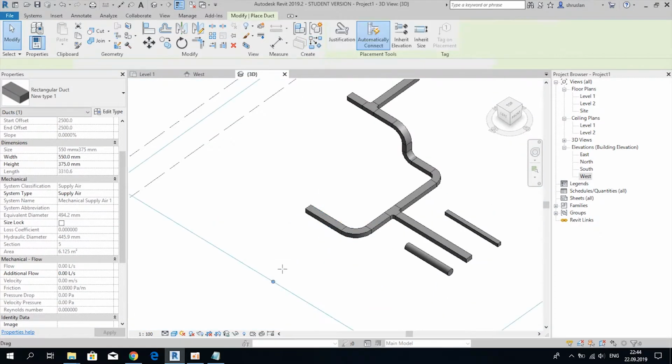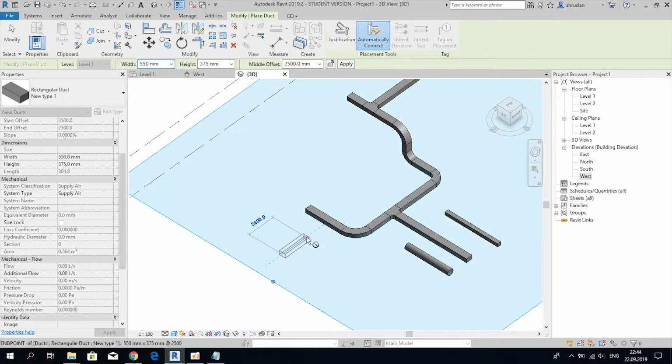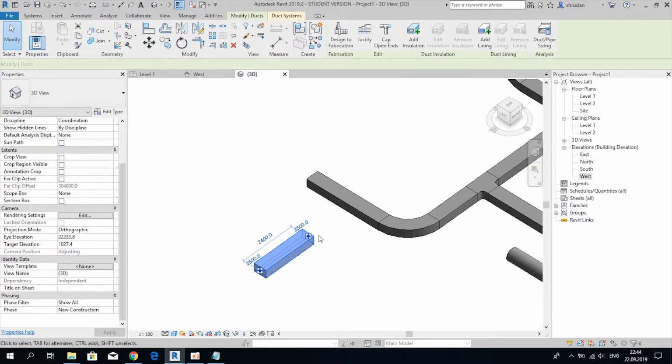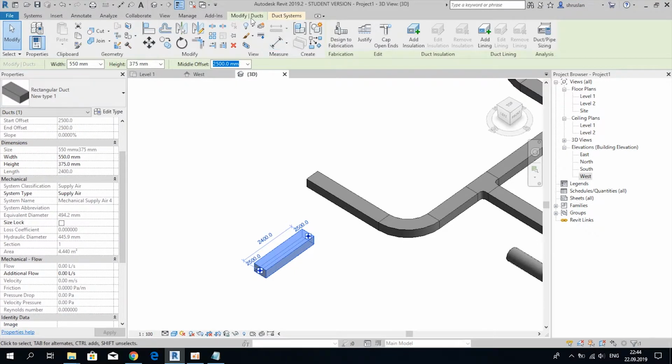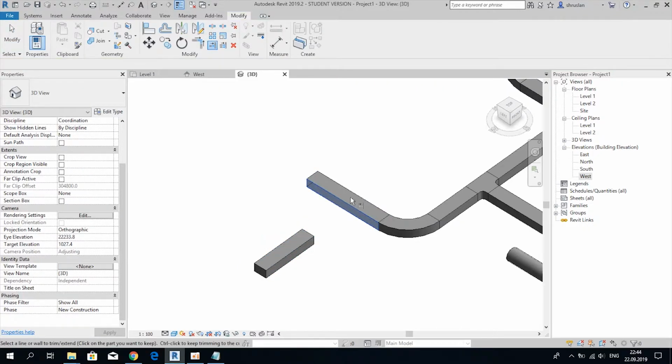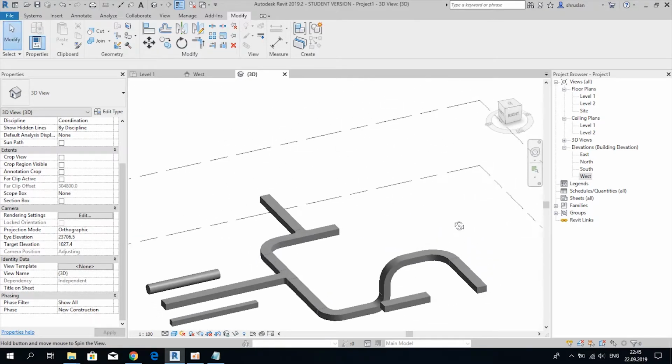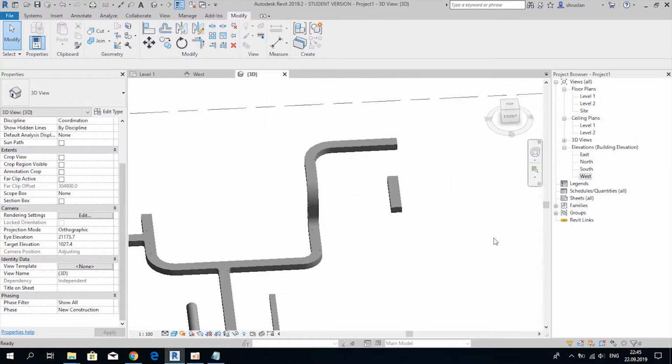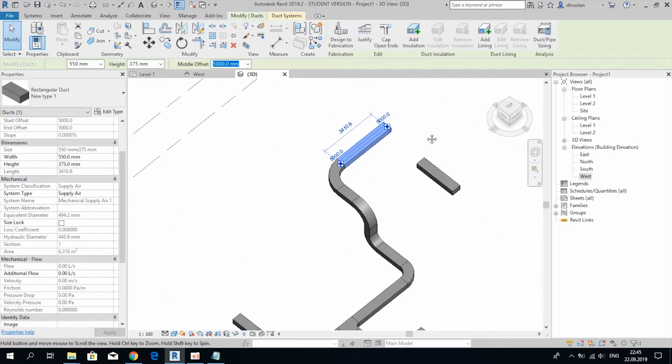If we want to connect the section to other line, we can use the modify tools like Extend Single Element. Select the plane, then element. See the result. Similarly, you can create the corner with Extend to Corner tool.